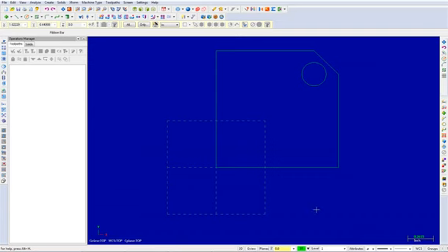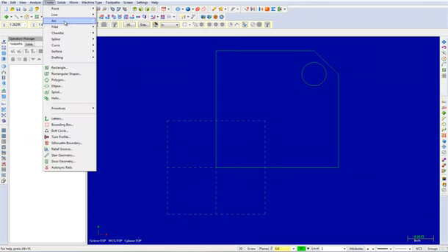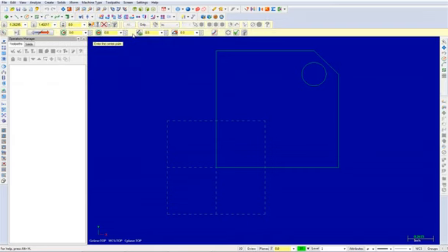We will now create the polar arcs. Select Create, Arc, Arc Polar. Enter the following values in the ribbon bar. Once complete, press Enter. Now, select the origin. From here, press the Apply button to stay within the command. Your part will appear as shown.